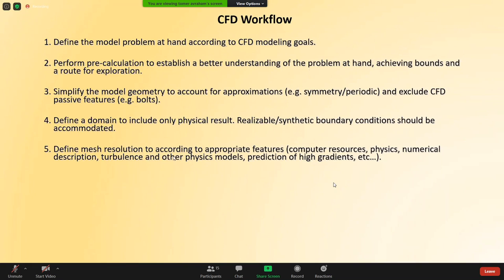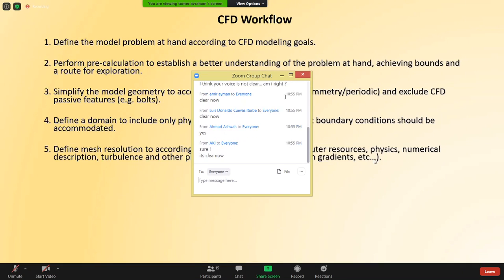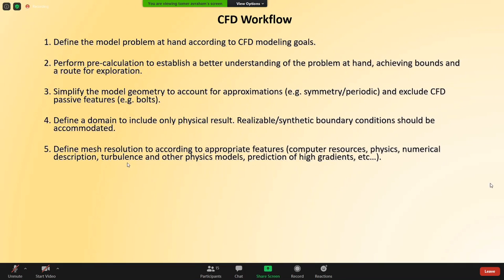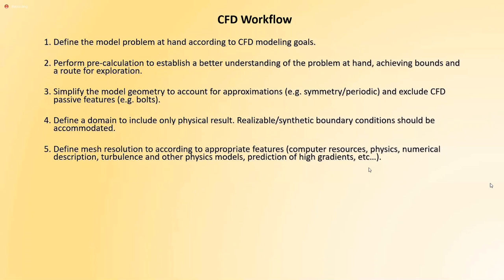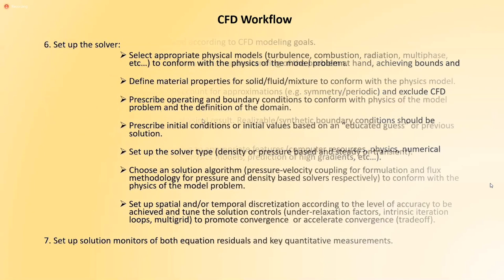Define mesh resolution according to appropriate features. Computer resources do count. Consider the physics, numerical description, turbulence, other physical models, prediction of high gradients, etc. Of course, we're going to get more into it in a second.